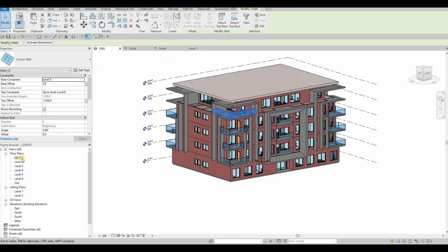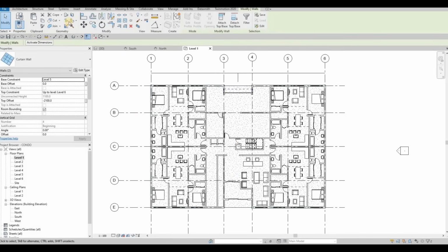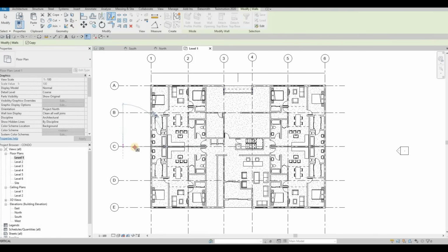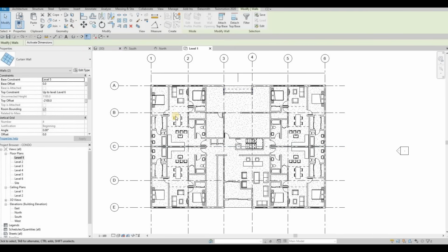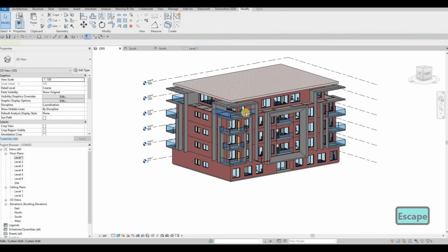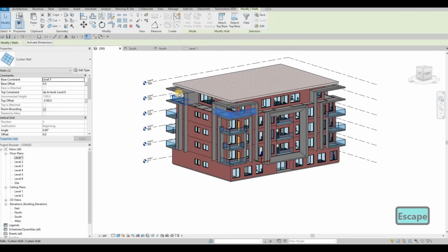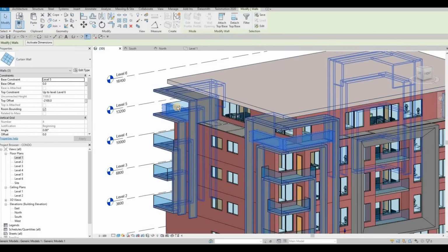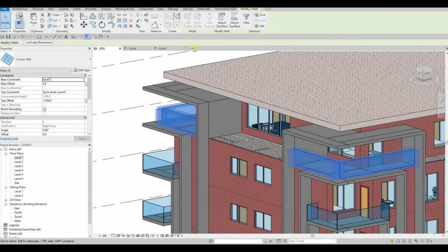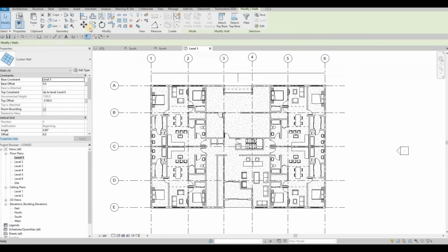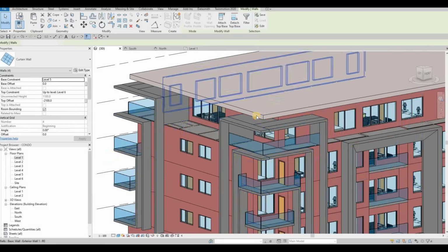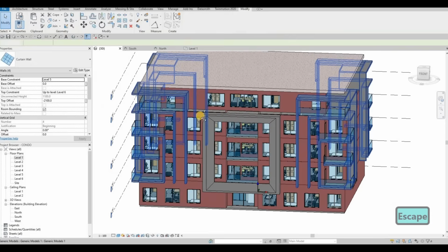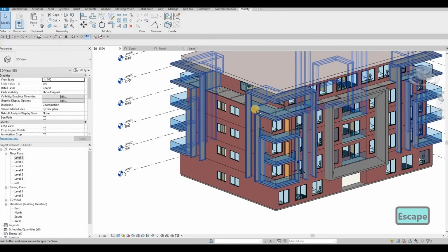So I'm going to go back here and mirror right here, and then let's use the draw axis for the next one. Select this one and then select this, and then if you check, we have them on the other side as well.